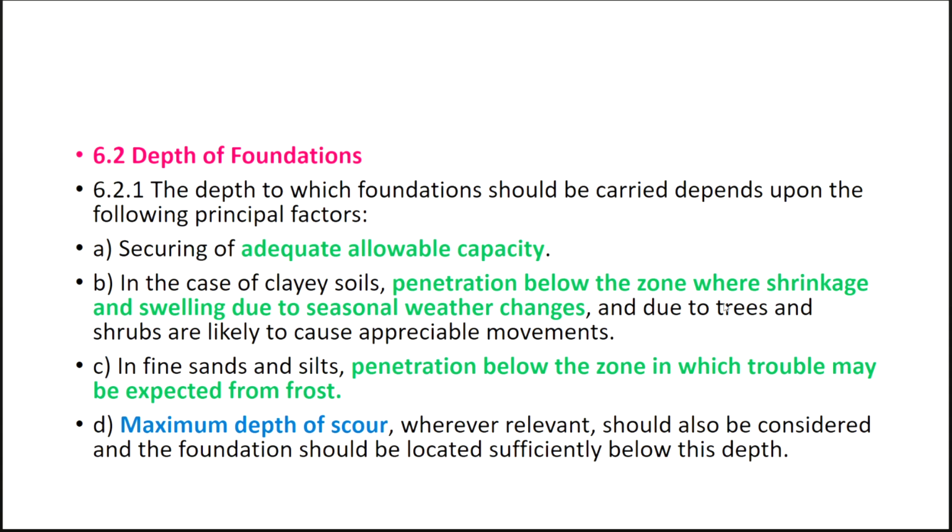In case of a clayey soil, penetration below the zone where shrinkage and swelling due to seasonal weather changes are there, I need to go below that, due to the trees or shrubs which are likely to cause appreciable movement. You may be having trees having roots. Then if the roots are at 3 meters, then possibly you will be required to go further below.